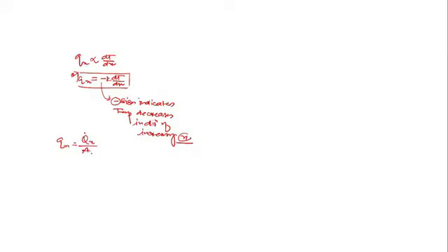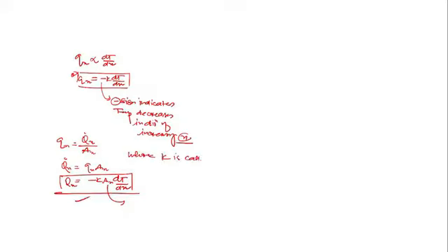And this is the flux, the rate of heat transfer per unit area, where the area is normal to the direction of heat transfer, A_x. Then you can also write the rate of heat transfer is equal to flux into area at that x, and this is minus k into A_x into dT upon dx. Is this clear? Where A_x is the area normal to the direction of heat transfer at that x. Any problem? Where k is called the thermal conductivity.